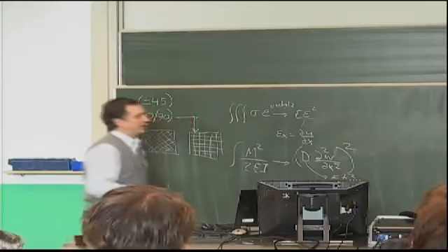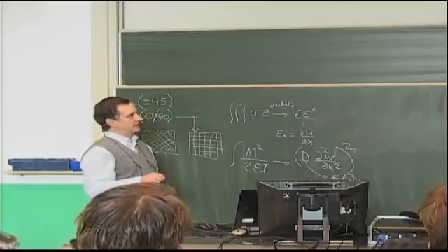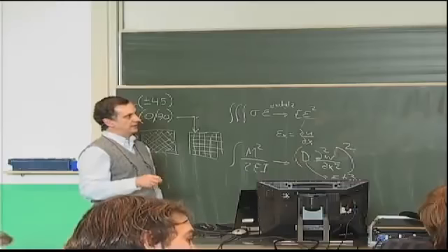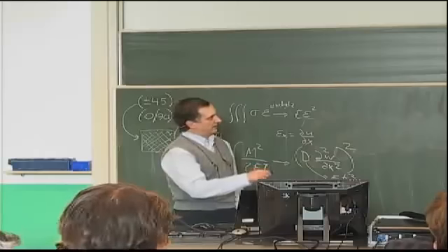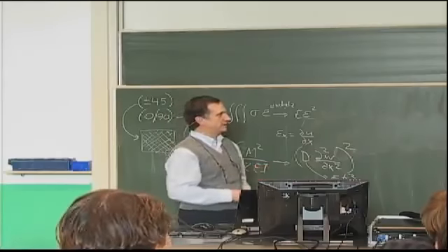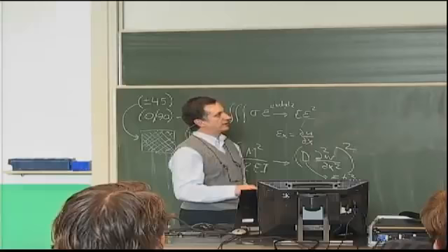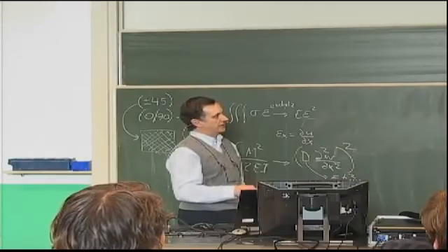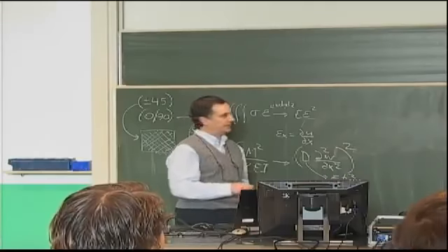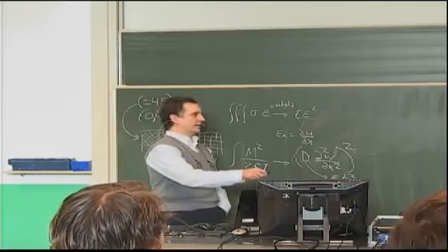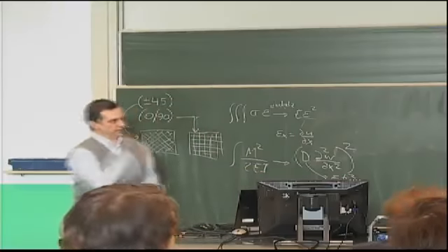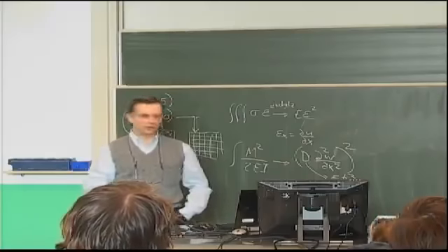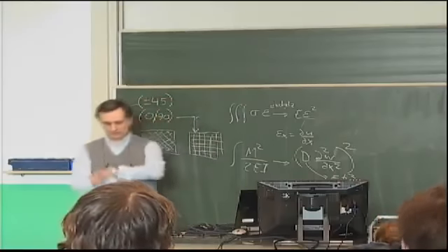We will also define normalized coordinates: xi is x over 2a and phi is y over 2b, to simplify some of the calculations. It's simply supported all around at the outer edges, and we apply a constant force on one end, NA, which is the force divided by 2b. Remember, N is force per unit width. So I apply a constant force F, which divided by my 2b width gives me the applied NA. And we want to calculate the stresses everywhere in this plate. Now, why we want to do that, we'll see in 15 minutes.